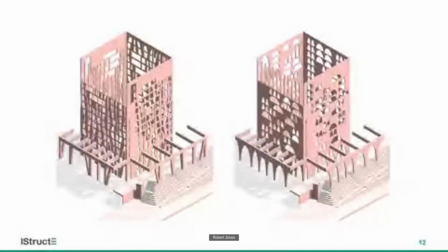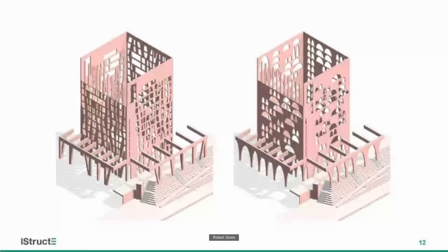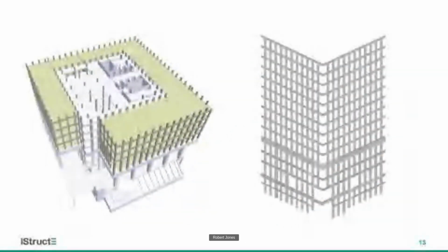The architects played around with geometries for the heart wall. They had a look at a trapezium arrangement, which is from a previous scheme of the building. They looked at a Toyo Ito arching concrete feel to it to make it feel like it's carved out of this one monolith of material. But we ended up with a much more regular column and beam arrangement, which was really well suited to a prefabricated approach where a lot of element sizes were repeatable, and there could be a real efficiency in the prefabrication of that.